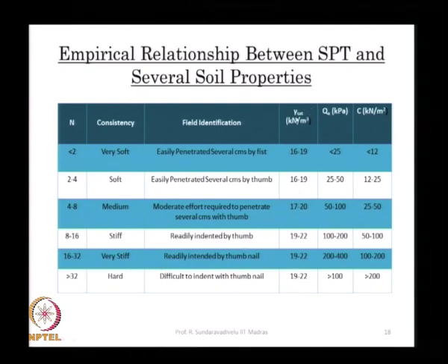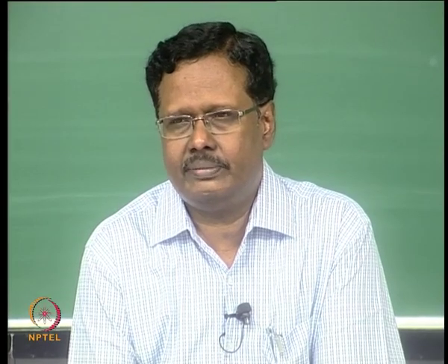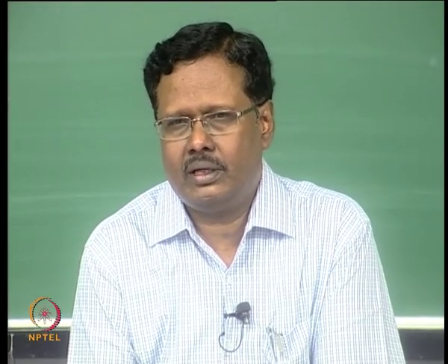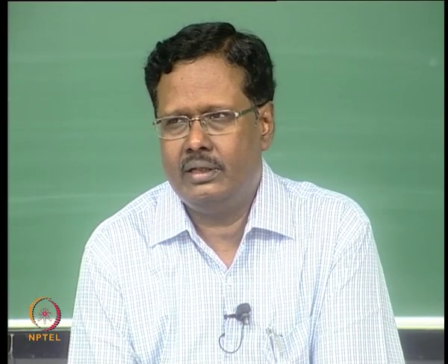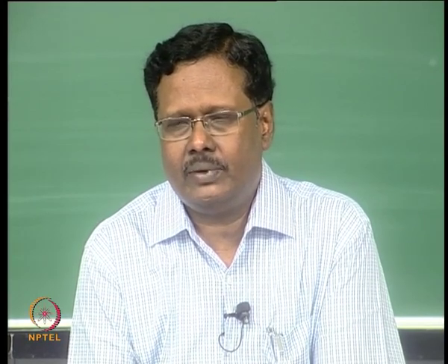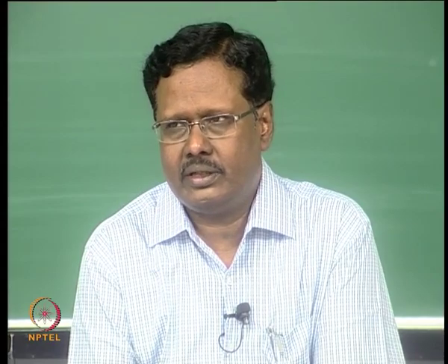Saturated density means you take the sample; with sand it can be easily explained. You pour water, it will take a certain quantity of water till saturation, then take the density. Soil is a 3 phase medium: you will have soil particles, water and air. If the air voids are completely filled with water, then it is the saturated density.